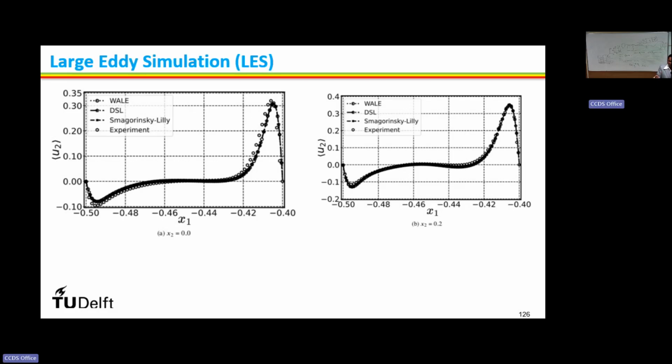The RANS result we feed as an initial guess to the LES to reduce the computation time. Sometimes starting the results from zero takes a lot of time. Initially we do a RANS. The RANS result, sometimes we use the velocity field and pressure field as an initial condition to perform LES. Right? So there is a lot of other computational stuff.